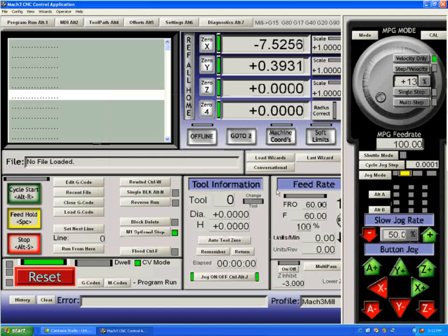And what that does is give you two speeds of jog. Just hitting the arrow keys on your keyboard, you can see I've got a speed of approximately 10 millimeters per second being fed. If I press the shift key at the same time, I now go to fast jog, and I have 20, which is twice the slow jog. In other words, slow jog is 50% of the maximum rate, and you get the maximum rate by pressing shift. Notice when I press the shift key that the fast jog indicator lights up. Otherwise, you're on normal speed.